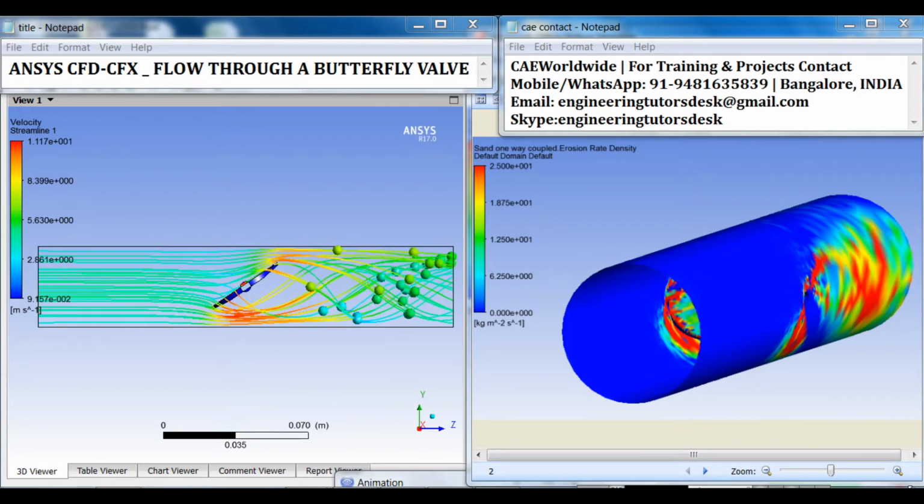An estimate of the pumping requirement can be calculated based on the height difference between source and destination, and head loss estimates for the pipe and any obstructions, valves along the way. Investigating the detailed flow pattern around the valve, however, can lead to a better understanding of why these losses occur. Improvements in valve design can be simulated using CFD, and implemented to reduce pumping requirements and costs.